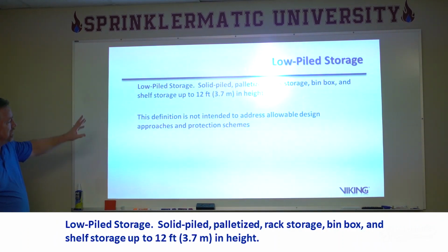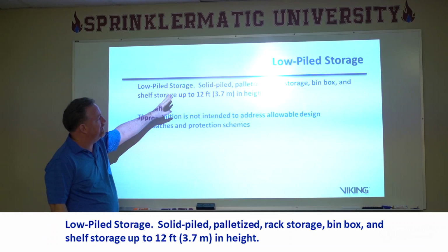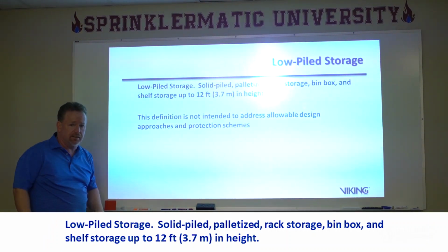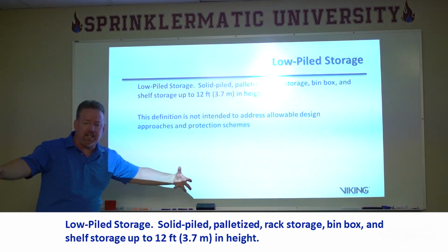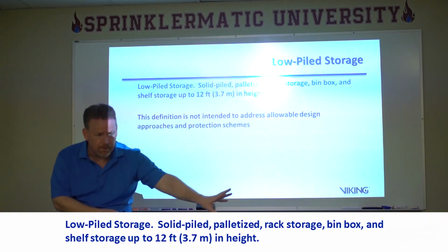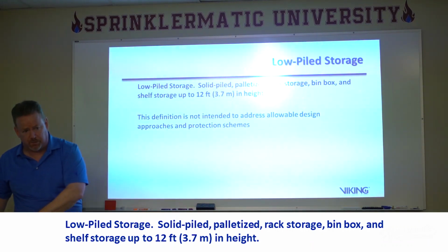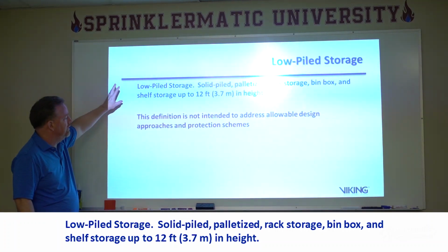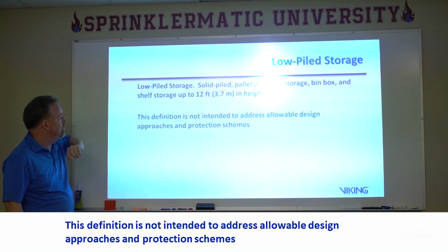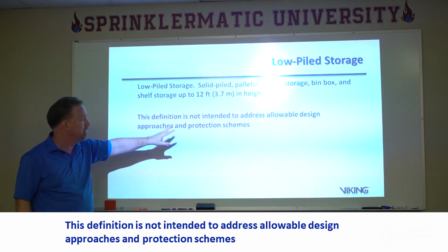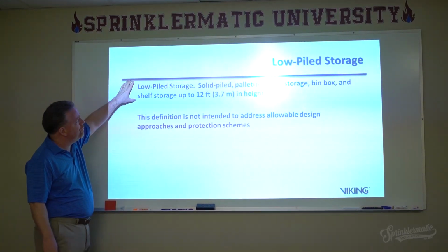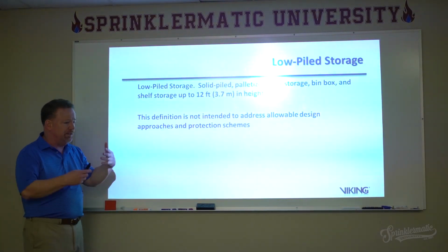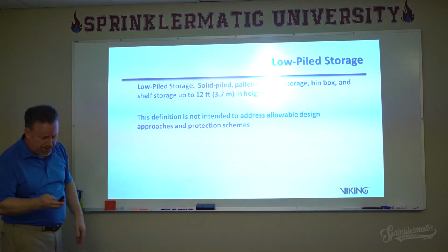So low piled storage is simply anything that's solid pile, palletized, rack storage, bin box, shelf storage, anything that's up to 12 feet in height. All right, so we've got this miscellaneous storage that is basically incidental to the other operation. Then we've got low piled. This definition is not intended to address the design approaches or the protection schemes, but instead is to say anything below 12 feet. If it's below 12 feet but you're in a warehouse, you treat it like low piled storage.